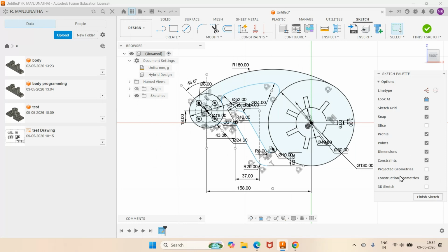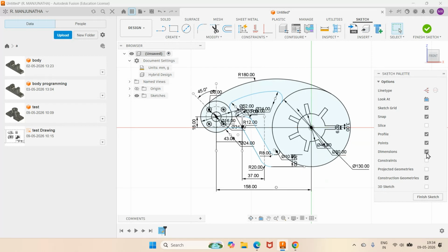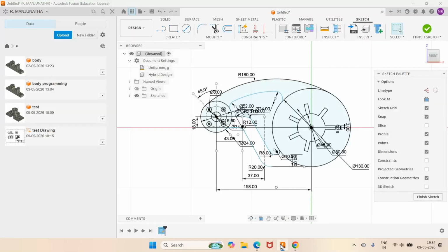And I'm constructing here. Okay. So the profile is geometrically constrained and also the profile is dimensionally constrained like this. Okay. So this is how you will be able to constrain this particular sketch both dimensionally and geometrically using Fusion. Thank you.